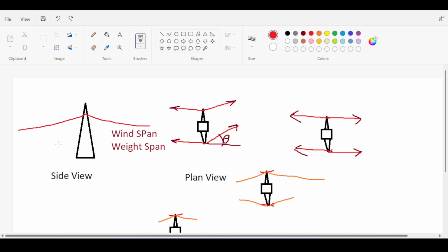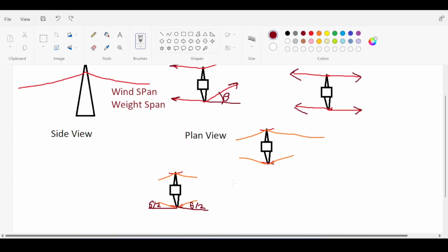What is not being ignored is the loads on the power lines, and this is why we need the ASCE guidelines. Because now you have here wind loads and you have here own weight. So you have the weight of the cable, you have the wind loads from the cable, and you have even cable load imbalances due to the theta here. So let's dissect them one by one.